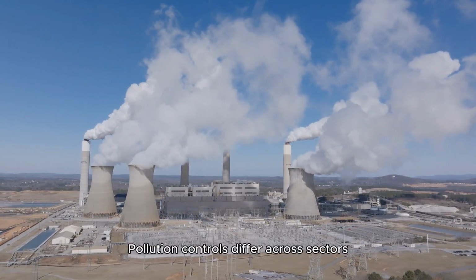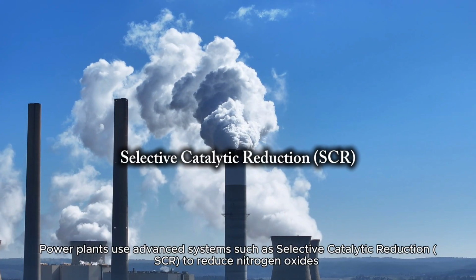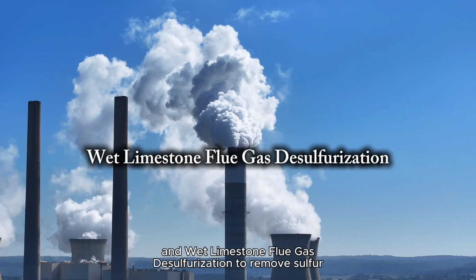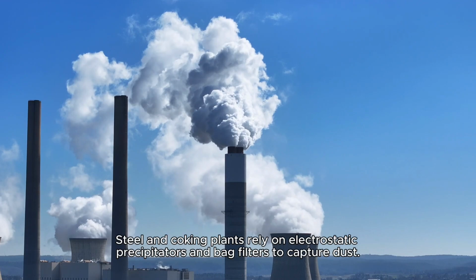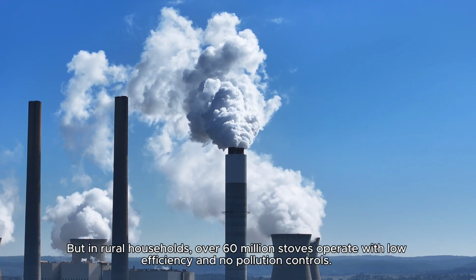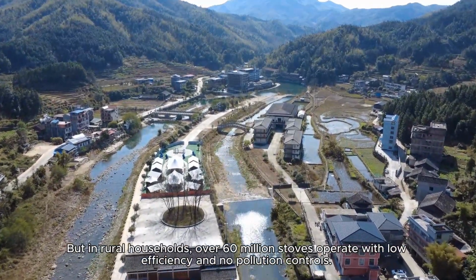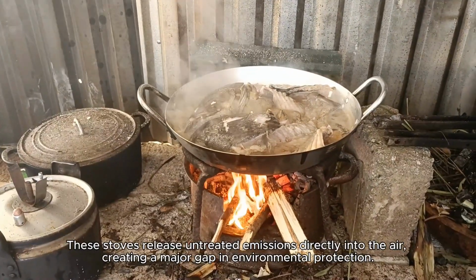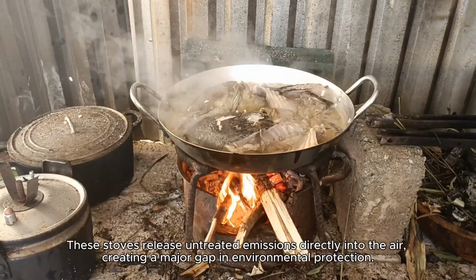Pollution control differs across sectors. Power plants use advanced systems such as selective catalytic reduction (SCR) to reduce nitrogen oxides, and wet limestone flue gas desulfurization to remove sulfur. Steel and coking plants rely on electrostatic precipitators and bag filters to capture dust. But in rural households, over 60 million stoves operate with low efficiency and no pollution control. These stoves release untreated emission directly into the air, creating a major gap in environmental protection.